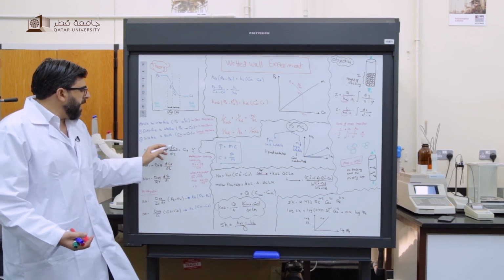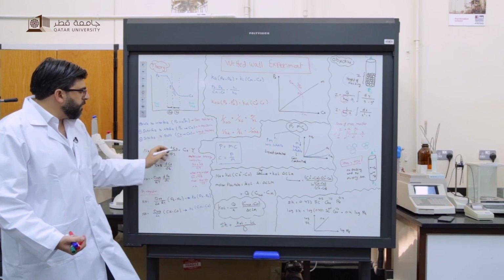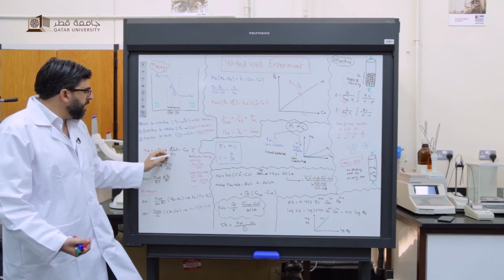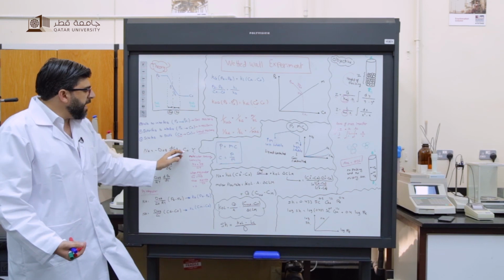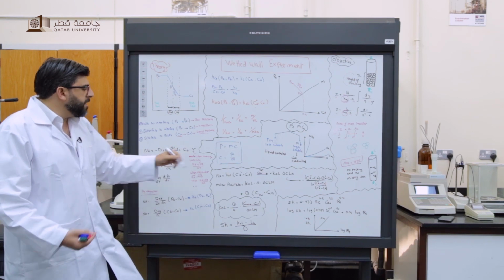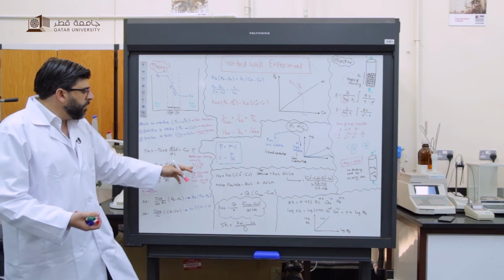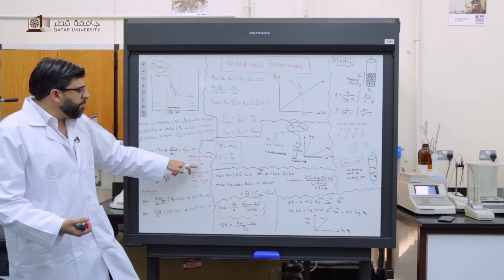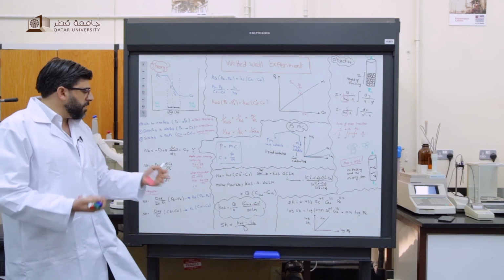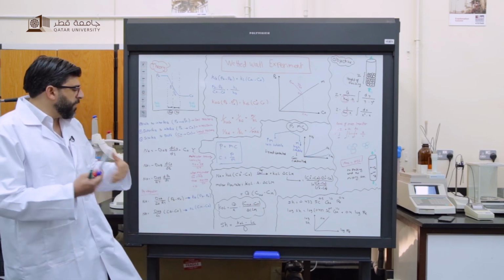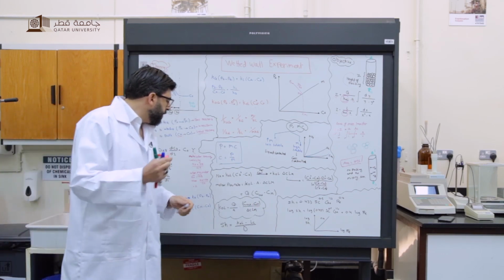Now, as you know from mass transfer, the equation for the mass flux is N_A equals minus D times dC_A over dz, plus C_A times V. V is the molecular average velocity, and it equals the flux of A plus the flux of B over the total concentration C_t, for a system of two components.